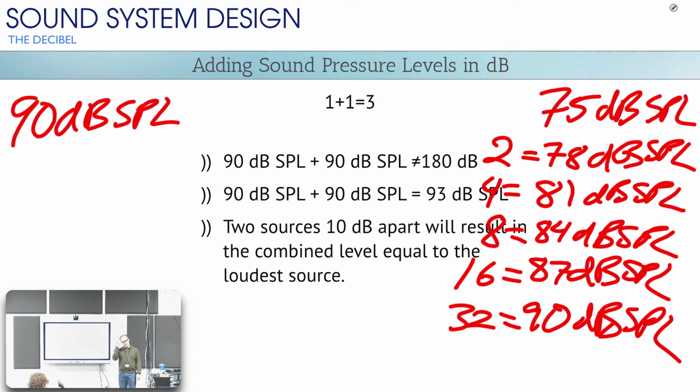And that's what line arrays do, by the way. So one of the reasons why you spend a ton of money on line arrays, instead of a single point source loudspeaker shooting out there, why you would buy 16 loudspeakers to point at the same spot, is because line arrays, and we'll get into this later when we get into directivity, have very specific horns in them that allow them to combine non-destructively. So they don't comb filter.